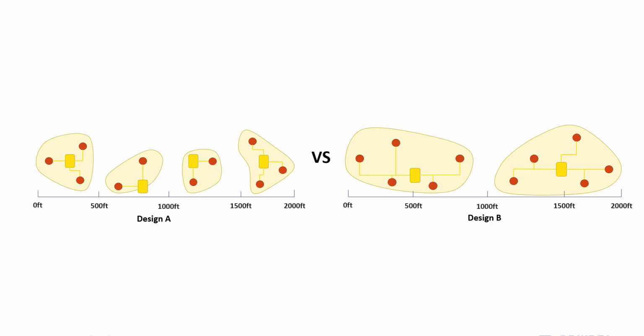You may also wish to set the maximum cluster distance to a slightly lower number than acceptable. This will produce smaller, tighter clusters. And in the event ComSoft Fiber Designer exceeds the maximum cluster distance specified, it is more likely all points will still be below the true maximum limit you find acceptable.